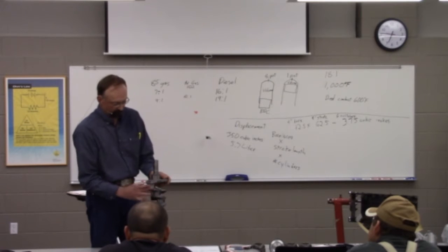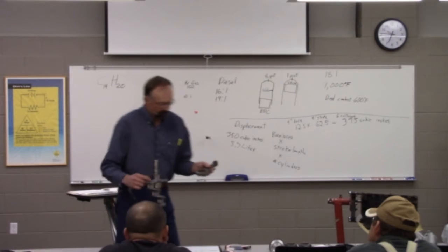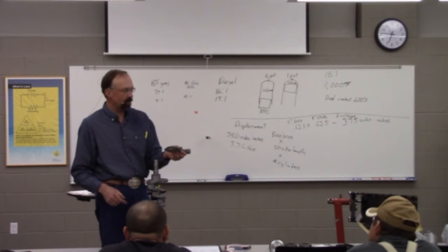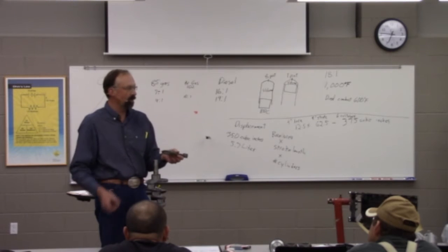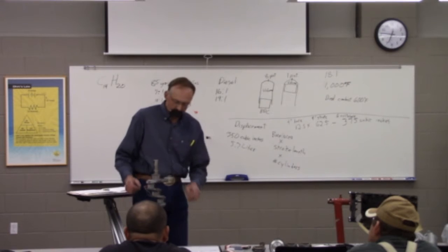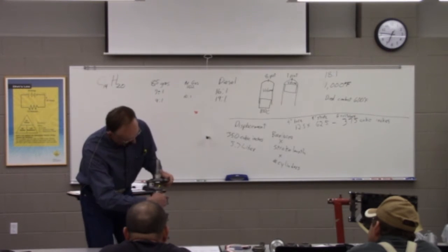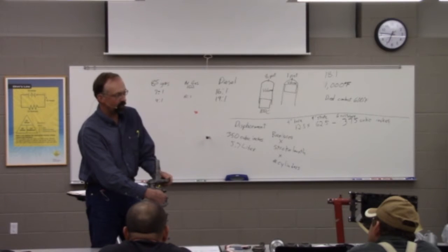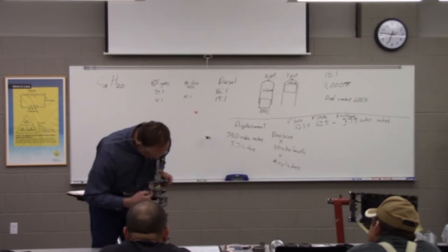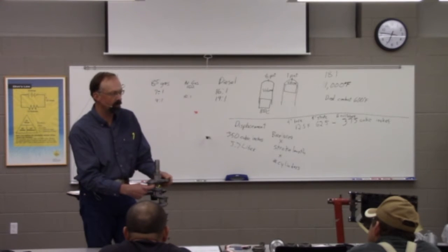So there's bearings here. These connecting rods hook here with these bearings, and like we talked, anywhere we've got motion, we need to lubricate it, right? So in our block, there's oil passages that push oil into the crankshaft through our main bearings, and then it will go through drilled passages and come out through the hole here to lubricate our rod bearings.